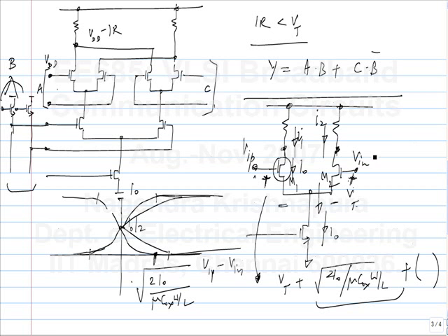See, Kirchhoff's current law has to be satisfied. So let's say this voltage is equal to this. Each one is carrying a current I0 by 2. Then now, suddenly, if you imagine the same gate voltage and the lower source voltage, each of these will be more than I0 by 2. That is just not possible. So both do conduct. When it's not completely switched, both are conducting to different extents. So is it okay? The triode does this thing?